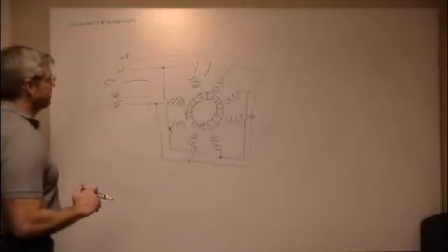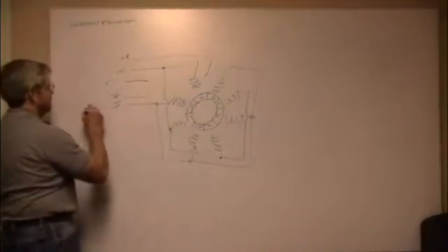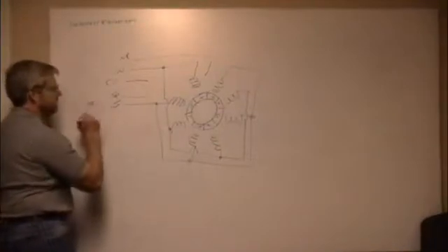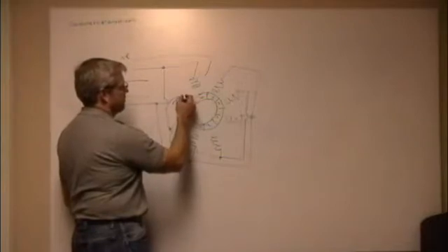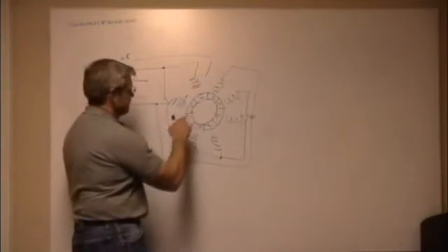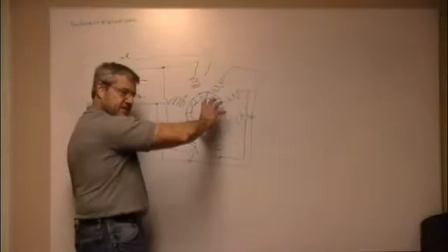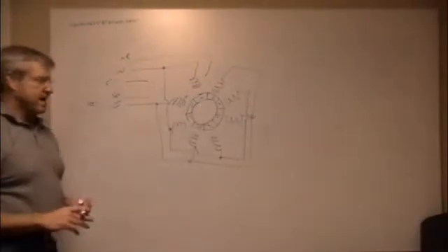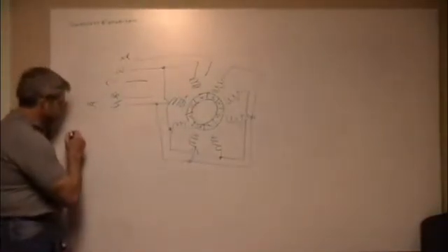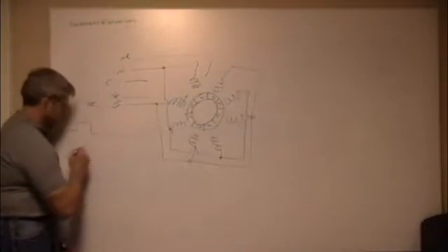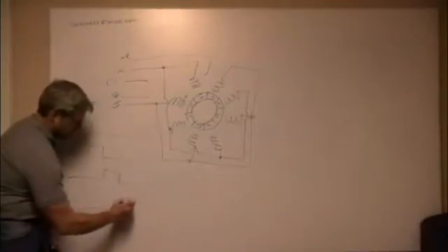We won't go too deep, but what happens is if I energize south, if I make this a high, then this is going to be a south pole, and it's going to repel the south, but it's going to attract the north, and he's going to take one step, tick, over. And so now what I can do is, it's a 4-phase system. It looks kind of like that.